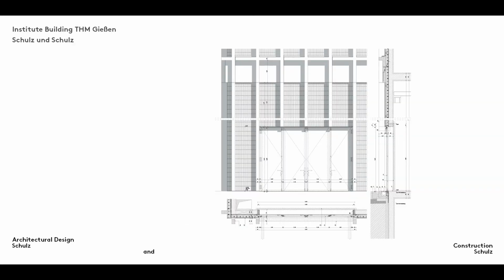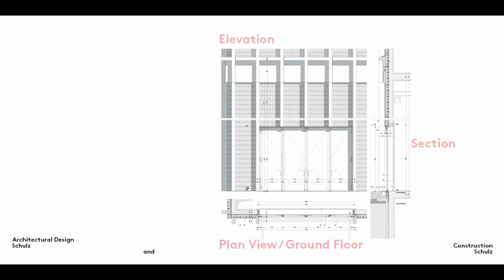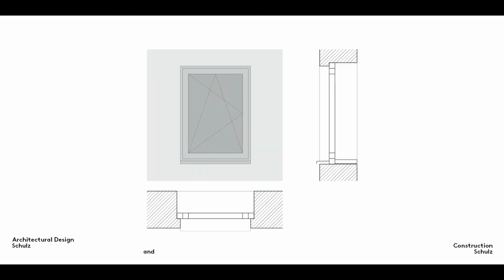To draw shadows in a facade elevation, you need the relevant plan and section views. The three drawings are arranged in relation to one another according to the orthographic projection principle, that is to say, with the plan view below the elevation and the section next to it. If we use the example of a building window, we can see how the shadows are drawn.